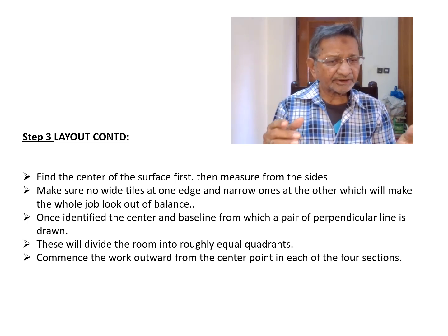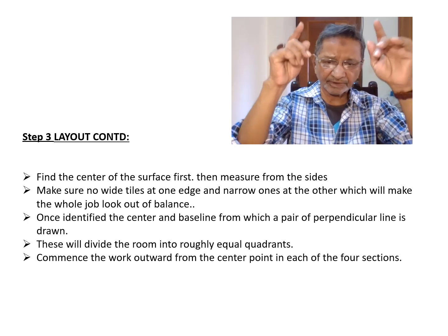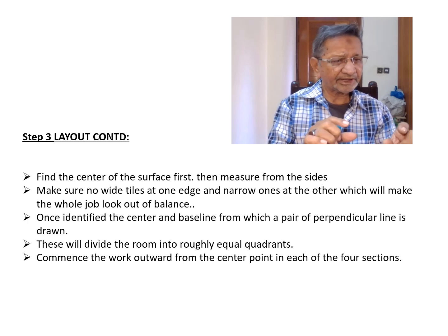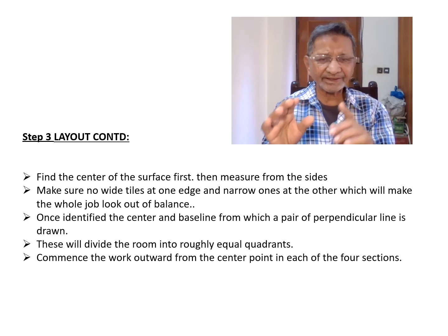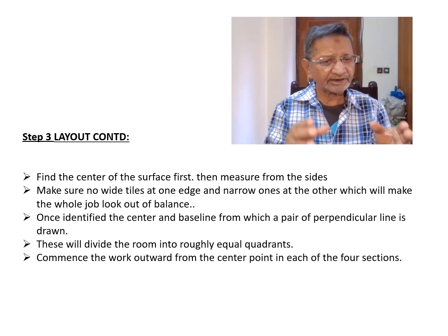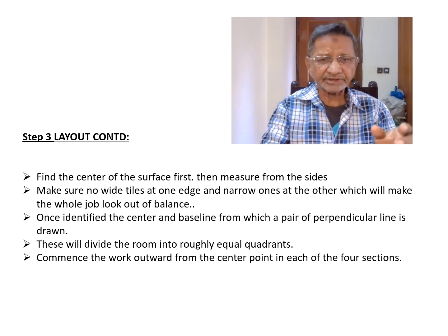Begin laying the tiles from the center, not from the side, not from the top, not from the bottom, but from the center, working out into each of the 4 quadrants of the room, ensuring each section remains aligned for a smooth, balanced finish.